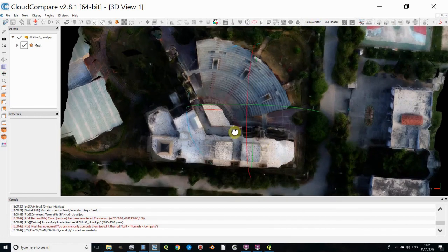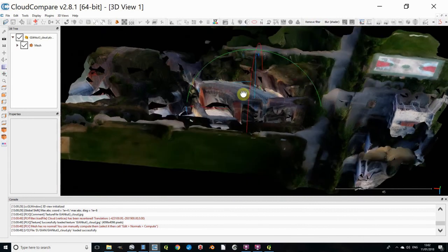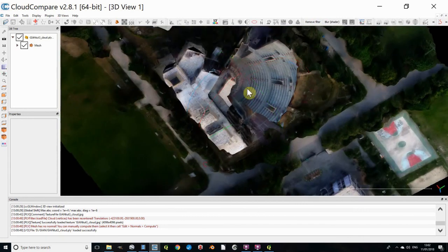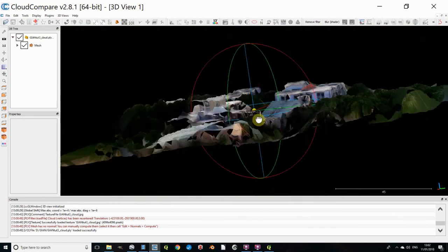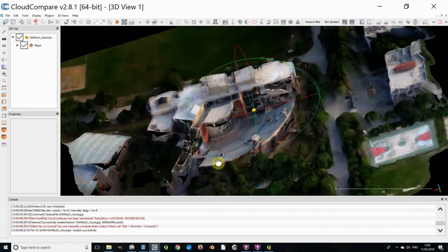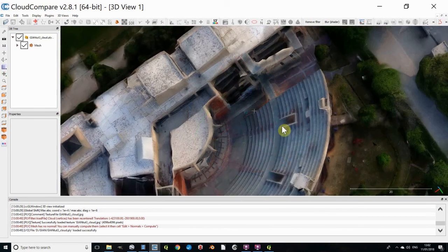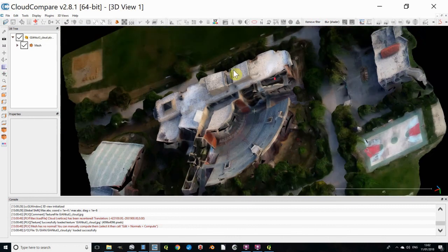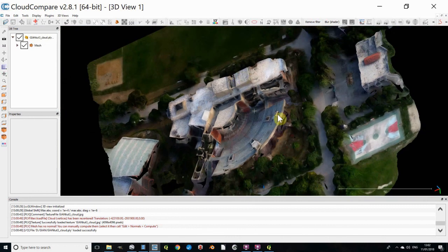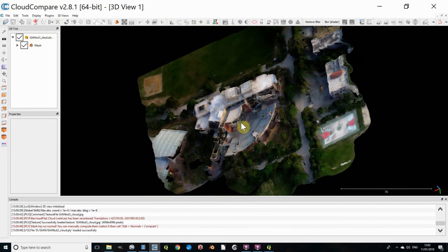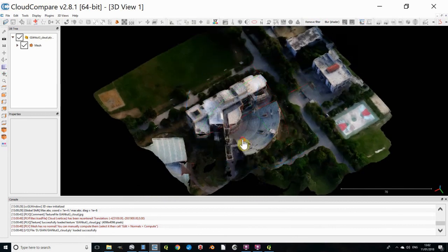But by working with point cloud analysis, as we call it, we can really get these 3D views. See, I'm actually looking under the point cloud now. There we go. There's the top of the point cloud. So this is a very much 3D processing approach. This software can allow you to compare two clouds through time, CloudCompare as it's called, and this can allow you to calculate, for example, the volume of a new building that's been built, things like that. So it's quite a powerful tool for visualization, and it works very directly with the outputs of the 3D software.